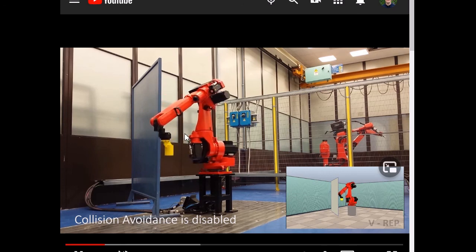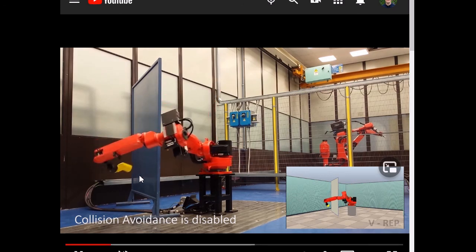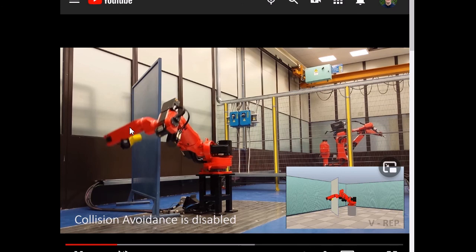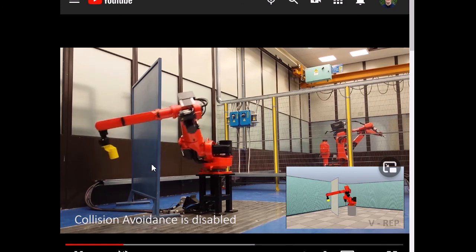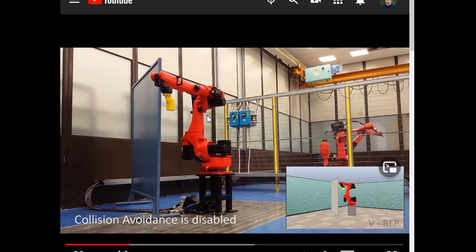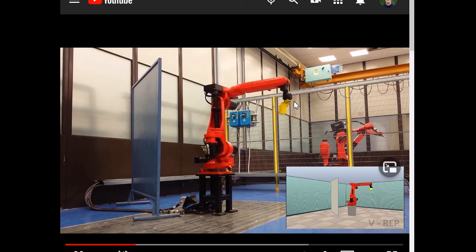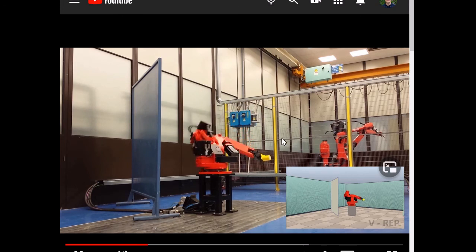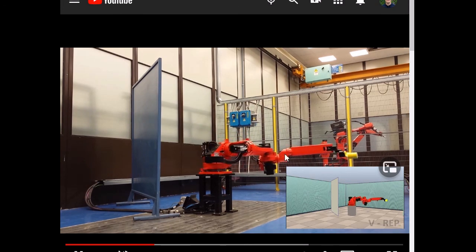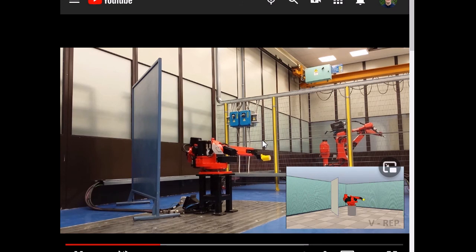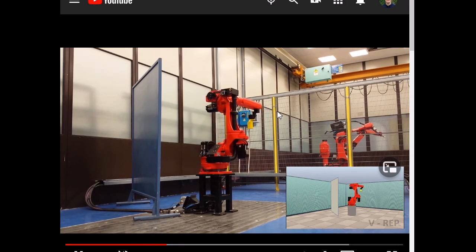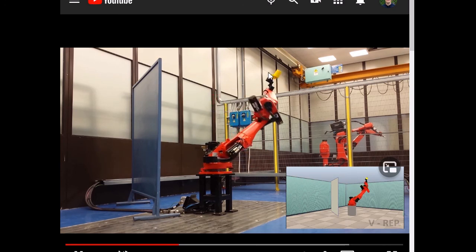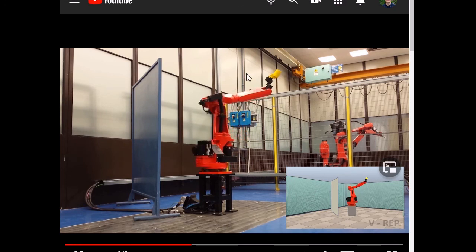And when it comes to the number of solutions, you can actually see that 7 degrees of freedom industrial manipulators offer you infinitely many solutions for some poses. That is, you can actually fix the object that you are manipulating in space while moving the rest of the arm out of the way.